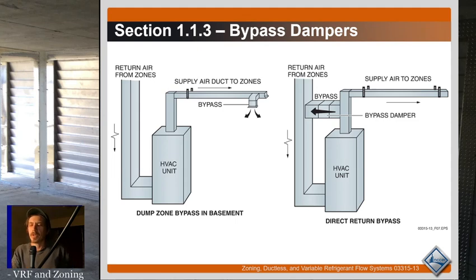Okay, so on really small motors, no matter what, it's very close to the rated amperage. The smaller the motor is, the more it tends to draw the same amperage all the time. But overall, the point is if you completely close the discharge side of a circulation pump, or you completely close the airflow on an air handler, your amperage will drop. It'll go basically all the way down, as low as it'll go. That's because it can't do any work at that point.